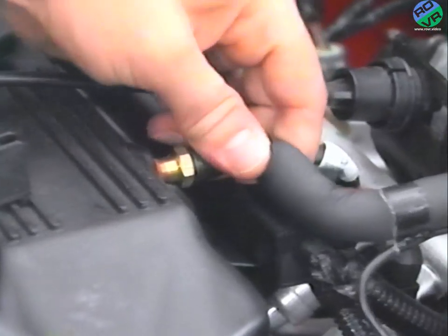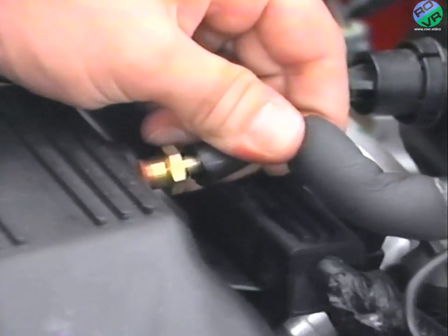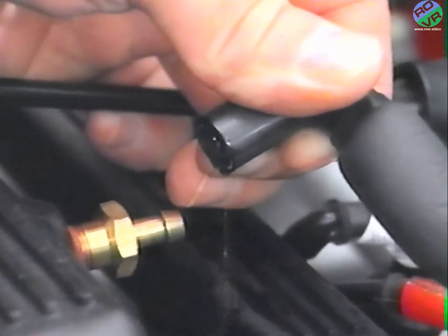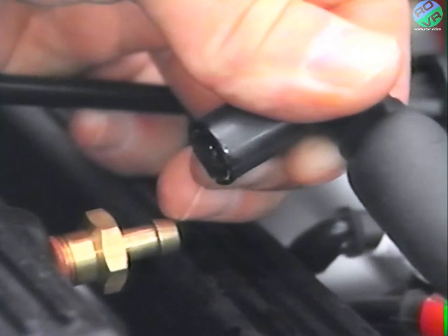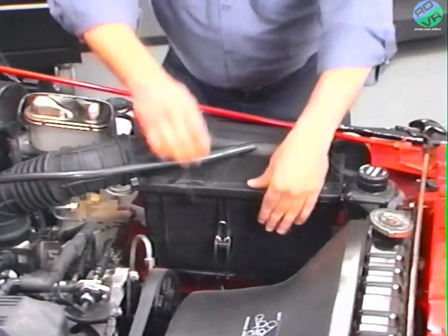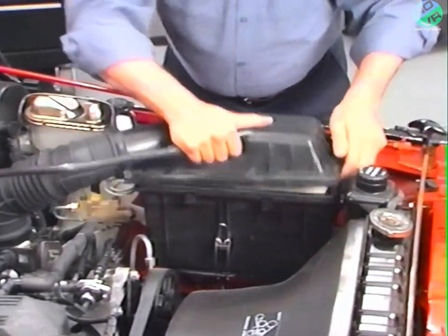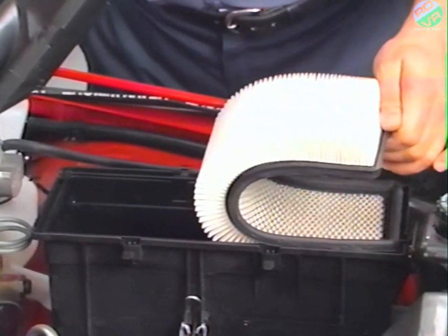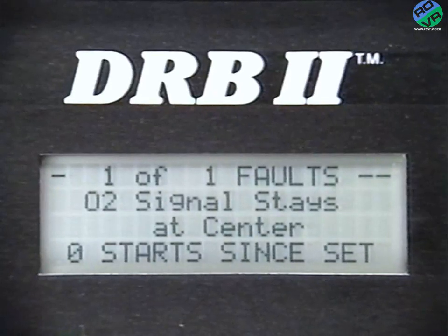Excessive oil consumption is also not monitored, although oil in the exhaust stream can cause the oxygen sensor to produce incorrect mixture readings. The engine controller does not monitor if the throttle body airflow is out of spec because of a clogged or restricted air cleaner inlet or filter element, but this can result in an oxygen sensor fault.